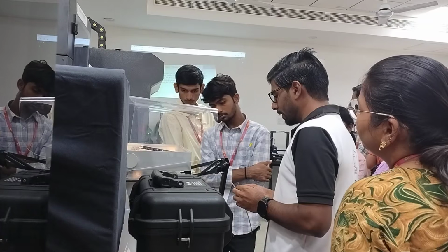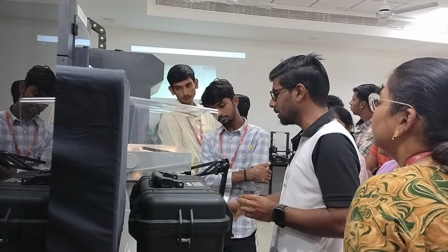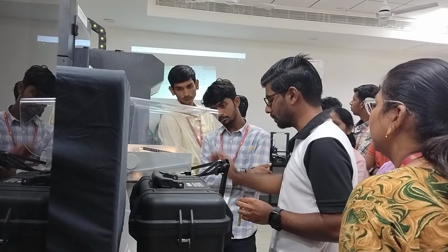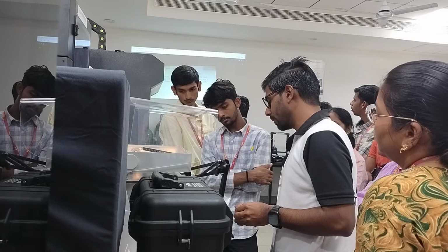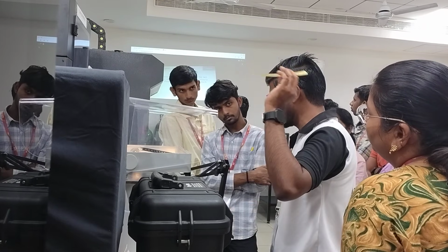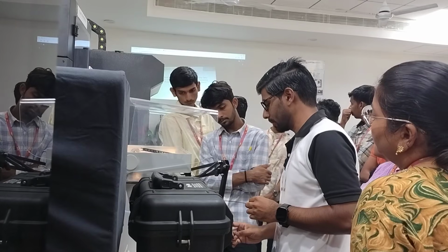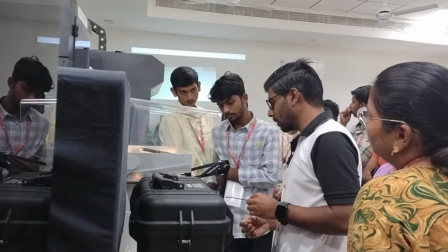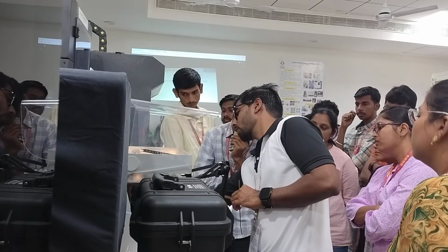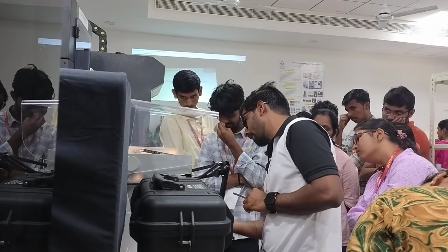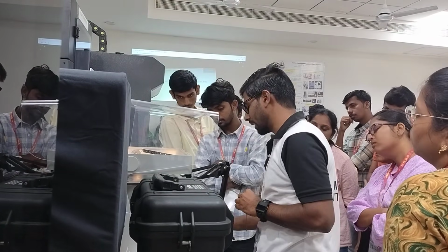Now it is telling me that during this process, do not rest your hand or put any pressure on the print bed, neither here nor on this machine. Next I'll click. To level your print bed you will need the two brass adjustment shims, and please press next if you are done with each of the steps. I click. Loosen the thumb screw until the print bed is at its lowest position. I have already done that. This is a thumb screw, thumb screw, thumb screw. There are 3 thumb screws. I loosen them so that the bed is at its minimum position. Then I'll click next.